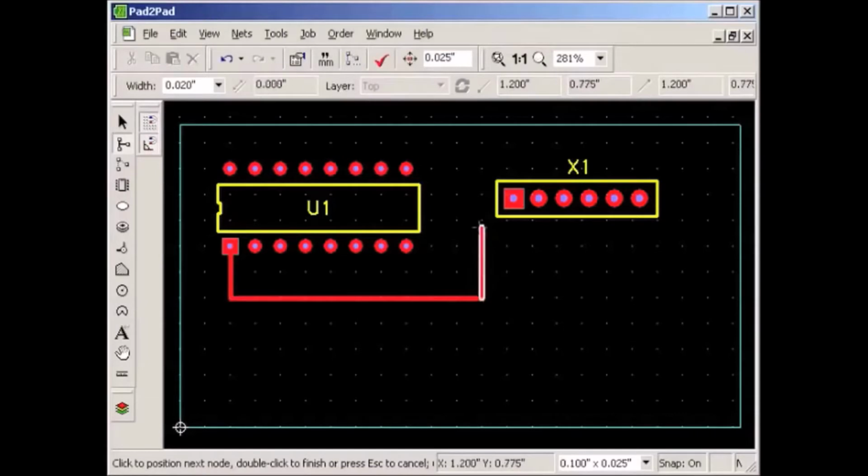Point the mouse to the destination pin and make sure it highlights. This will ensure the trace stays locked to the pin if you later move components. Left-click at the destination pin. Notice that the trace can continue on to another pin. Right-click to end the trace.